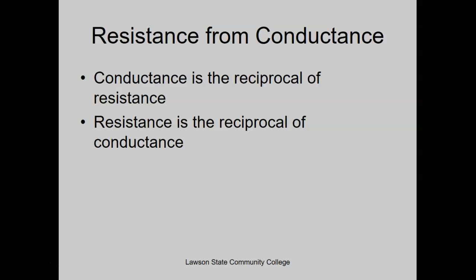Resistance from conductance is where you take the reciprocal of resistance to get conductance. So thus you take the reciprocal of total conductance to get your total resistance. You take the reciprocal of the reciprocal. Yes, you do. You flip it, add it, flip it back.